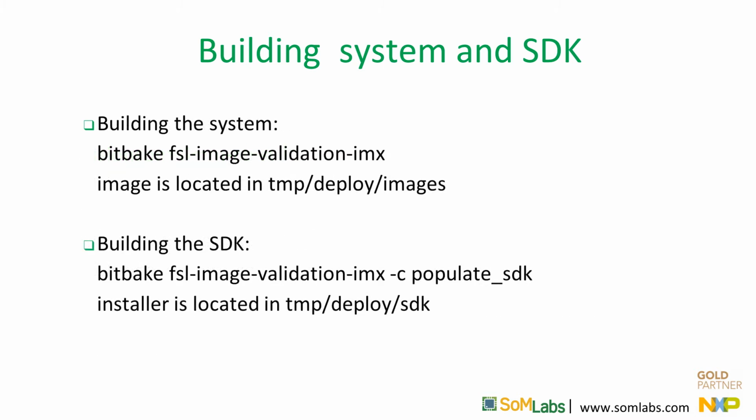At this point, we can start the long compilation process by calling bitbake fsl-image-validation-imx. This command may take up to several hours depending on the available hardware resources on the host machine. For this reason, everything has already been built on a virtual machine and you do not need to build the whole thing for the webinar, only the changes that we will apply later during these exercises.